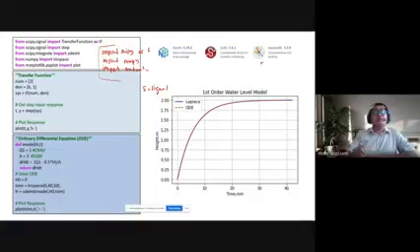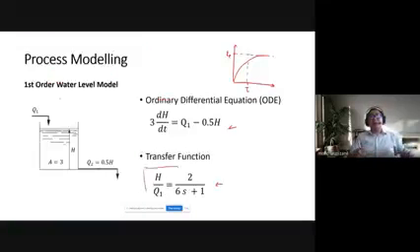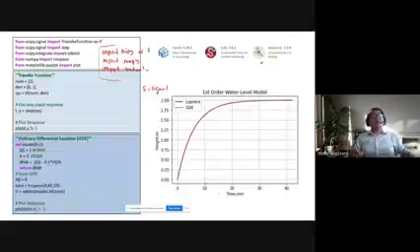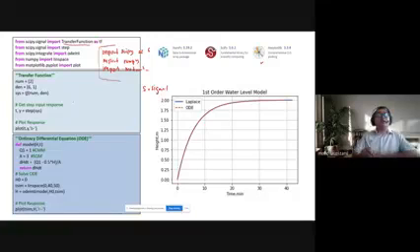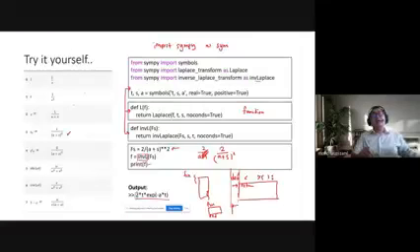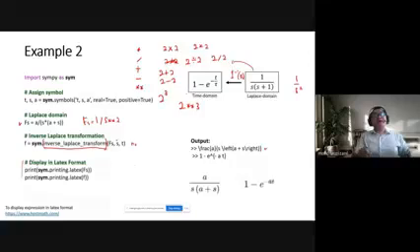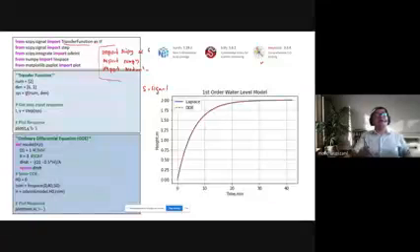Okay. So for this transfer function, first of all, I will discuss this part. So how we do the process modeling if you have a transfer function, and in the transfer function we assign something like this, TF or transfer function, right? It's just like earlier Laplace, it looks like the Laplace transform, right? Like the Laplace inverse Laplace transform. So this is the function that you call. In this case, I'm using transfer function.